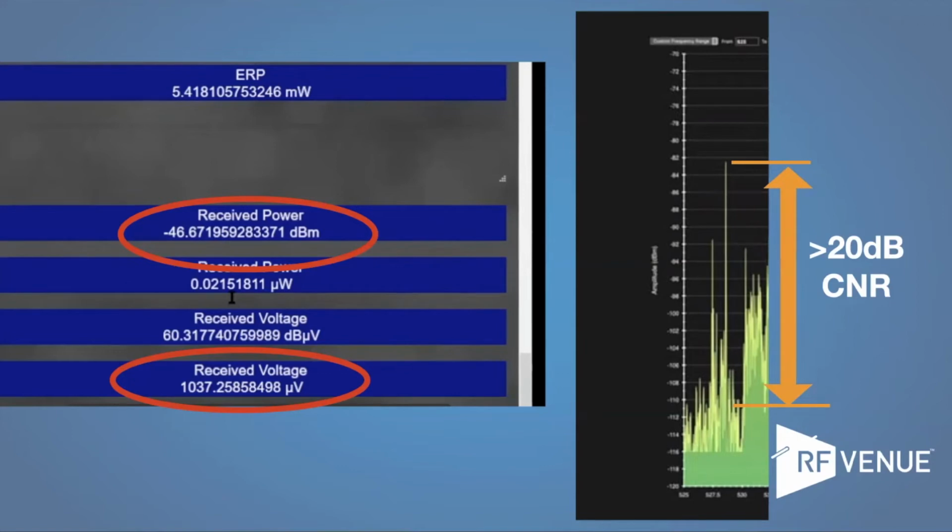If there's going to be nobody there to deal with this, if you're an installer putting in a system at a school or something, and you've got the boys' vice principal in charge of this, well, I'm guessing he's probably not a radio expert. You're going to want to set that higher. You want to know that you have more than 20 dB of carrier to noise ratio. But that's the goal. This is arbitrary. You set it wherever you want, but 20 is getting right to the edge of where, when somebody turns around, they could go off the air.